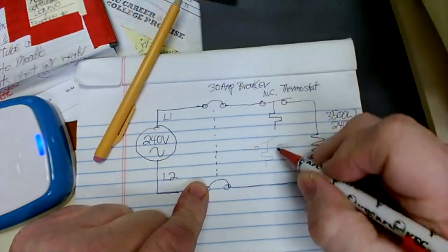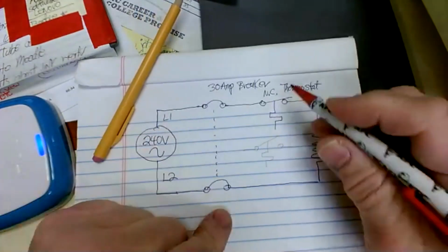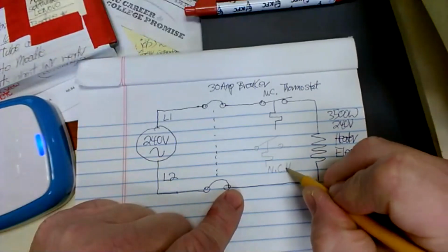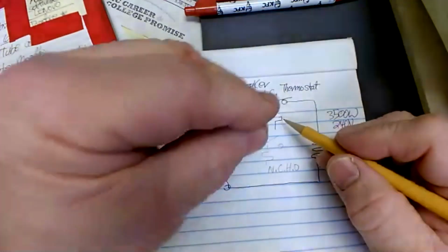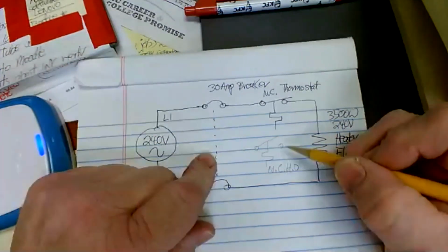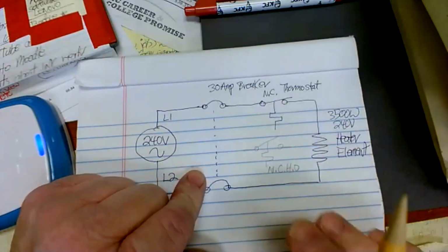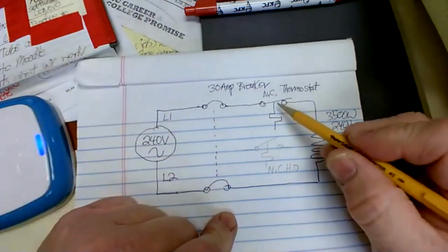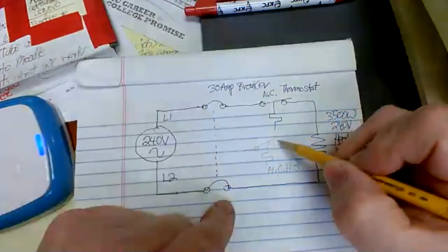Normally closed thermostat. Now, when it's open, it's still a normally closed, but it's normally closed held open right now. And that'd be NCHO, normally closed held open. It's held open because the thermal has sensed heat. It's still a normally closed, but it's being held open. Everybody got that? This is for motor controls that you'll learn in January. But I'm showing you that so you can understand the heater element itself and what actually runs it. So it's run completely off of that one contact. And as it gets hot enough, it pops open like this.